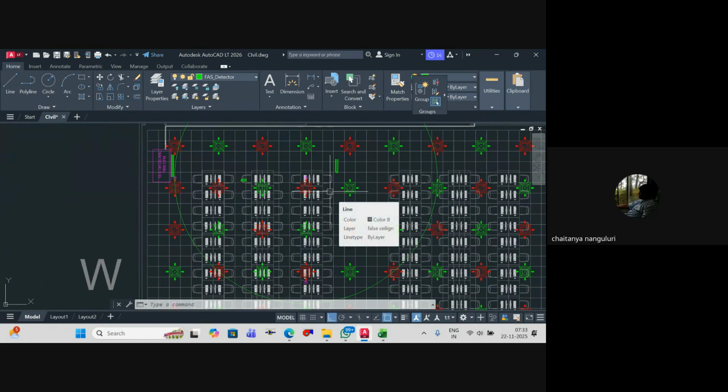What is the reason, sir? Because from the supply air grill, air from the AHU will be coming out into your room space. So if the fire is inside the room space, the smoke has to enter your AHU. It has a filter, that filter will clean it, and then you have your cooling coil. The dust might settle over that, and only then does it enter your space. So what will happen? It might not detect fire, though there is smoke. You agree?